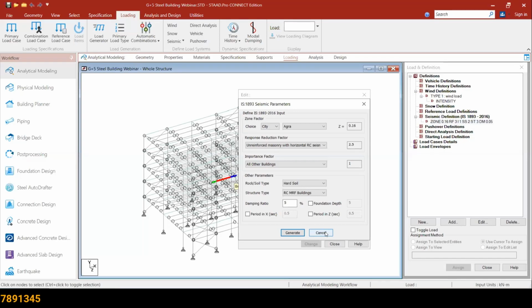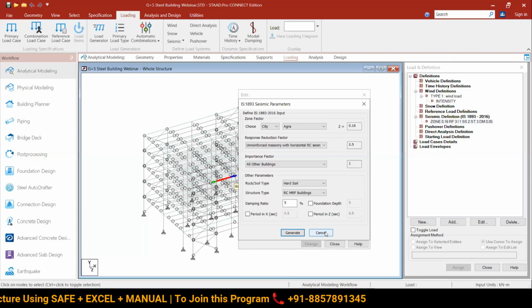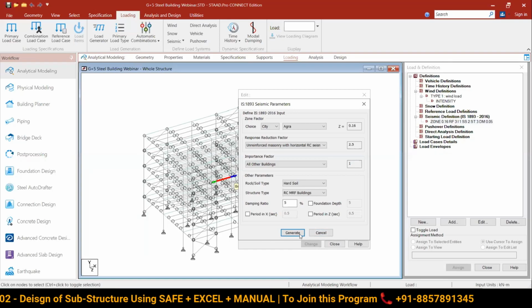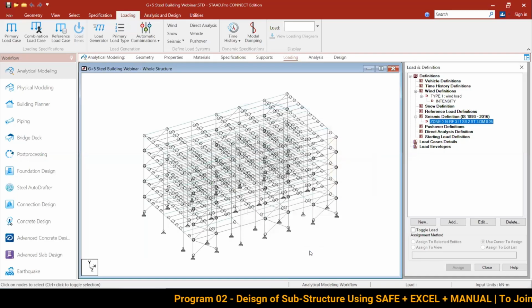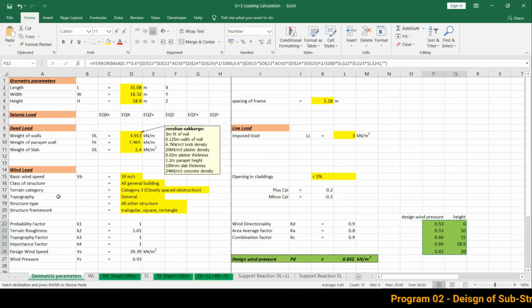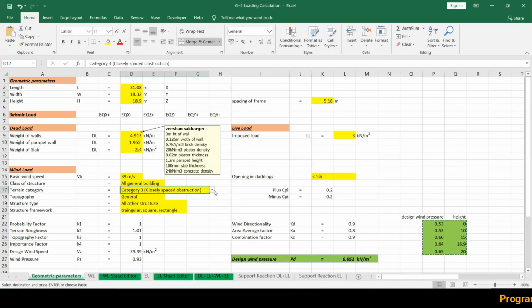If it is 101 or 103, whatever, based on the mean sea level, we have to feed that. So not from zero. You are speaking regarding wind load? So I'm asking about this wind load intensity. Regarding the wind load intensity, this depends on my terrain category, which I've already chosen. Yes, that's correct, because the height is measured from existing ground here.